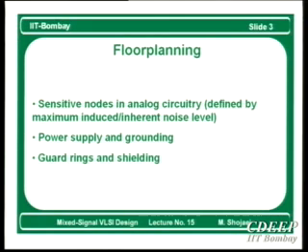And then when we do floor planning, we have to be careful how we want to route the power supply and ground afterwards. It's not that floor planning and routing are independent of each other, because it depends how you put the VDD and ground or VSS lines. Because VDD and VSS are not clean. Always they have a lot of noise. The reason is that we are talking about a mixed signal system. In a mixed signal system, you have a digital module with a lot of switching. Therefore, your VDD and ground are not very clean.